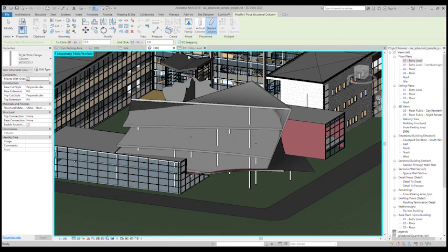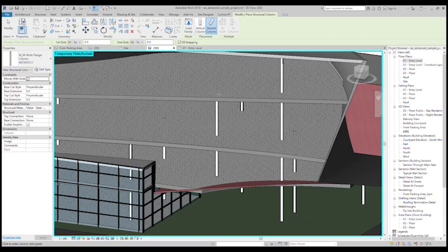Now, as I'm hovering over these existing columns or the existing floors, I can draw 3D columns to those corners. Very important for columns, when you're using 3D snapping on slanted columns, you can snap to anywhere on an existing column, its draw line or its endpoints.